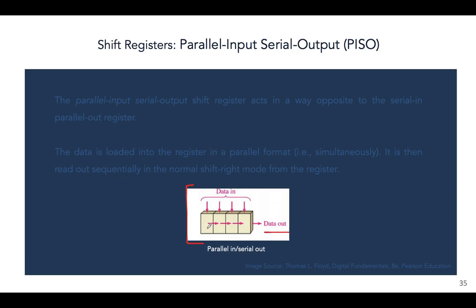And you have to understand, see, when the data moves in, so suppose we have a 4-bit number 1010 that is entered into the register, but the outputting of the data has to happen sequentially, which means that when the bit stored in this location is read out, then the bit stored in this location has to move one position to the right so that that bit can then be read out. And then that bit is read out, so the bit that was initially stored in this register has to be moved here, and then again it has to be moved here so that the next bit can be read out, and the same goes for the 4th bit. Right, so this is where shifting is involved.